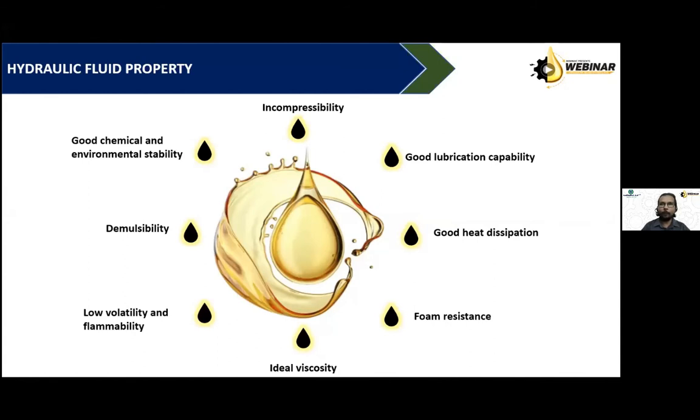Then foam is one of the big enemies for a hydraulic system. Foam contains air. Air is compressible, so we lose the incompressibility of the fluid when foaming is there. Then when foam enters into a high pressure zone, it will rupture or burst. Bursting will cause micro drizzling effect, cavitation, pitting. Sometimes it will promote the galling effect if it enters into small cracks.